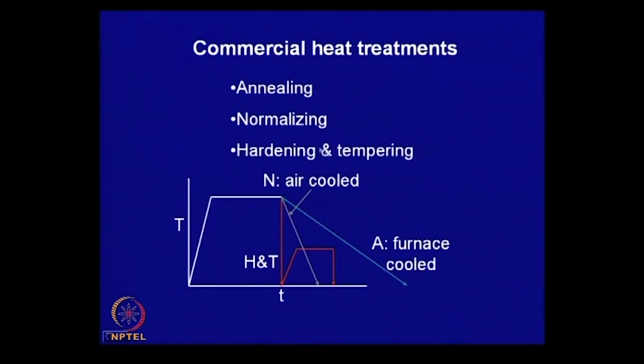And we will see when you harden, since when martensite forms, the surrounding lattice will undergo tremendous amount of strain, which is accommodated through slip or twin. So, this introduces a lot of strain, and therefore the structure is highly unstable and often susceptible to cracking. So, it is given a treatment called tempering.